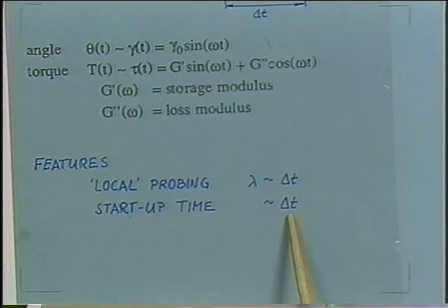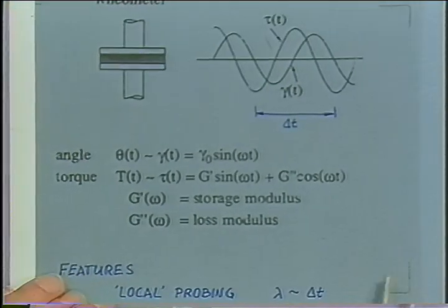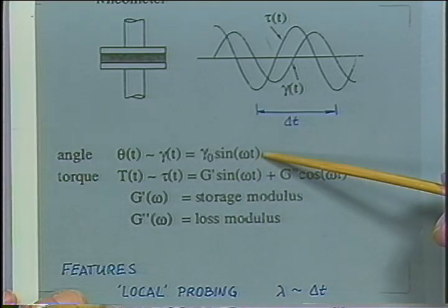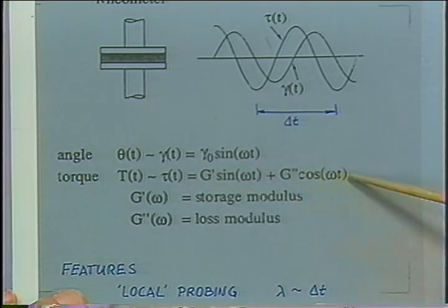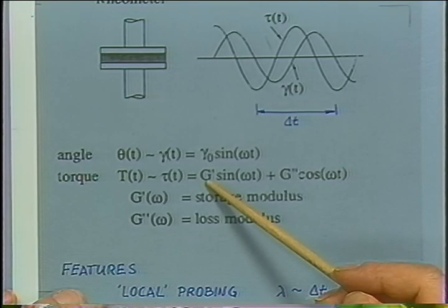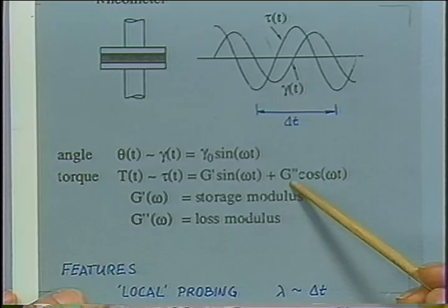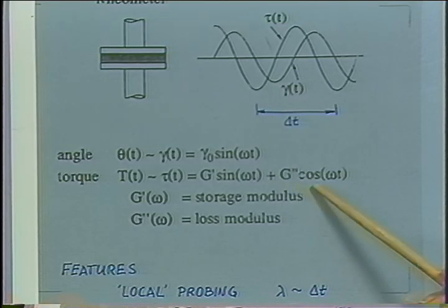So it's a spectroscopic technique which allows us to pick relaxation phenomena from the overall spectrum by just choosing higher or lower frequencies. Now that's used in the following way: imposing oscillatory shear and measuring the stress response gives us an in-phase part of the stress, the stress which goes with a sine function in time, and an out-of-phase part which goes with a cosine in time.